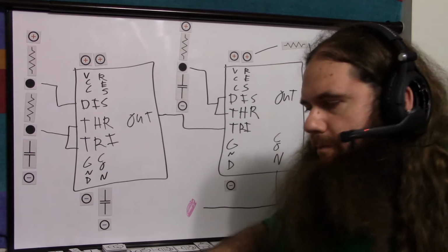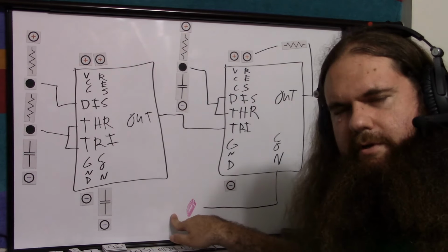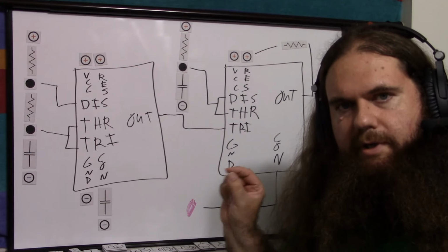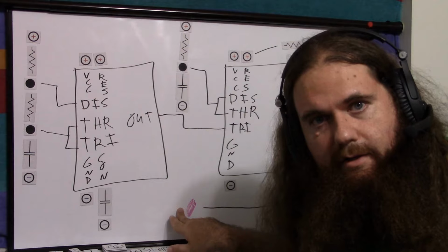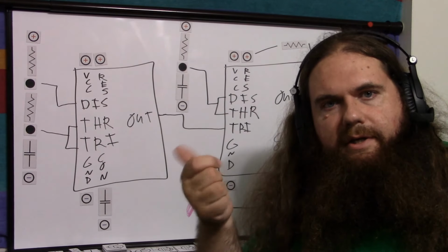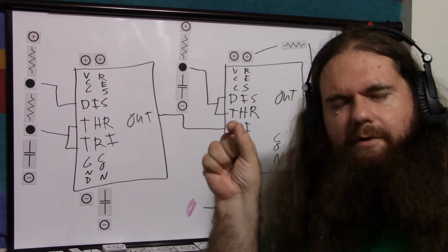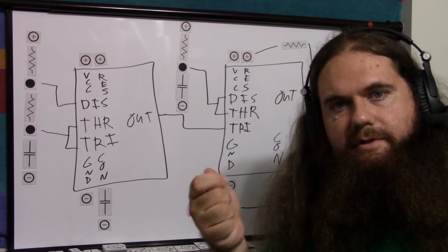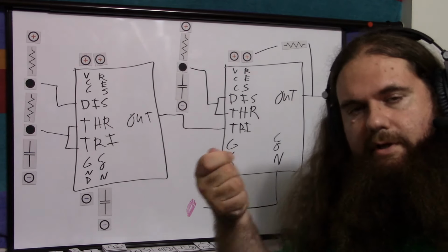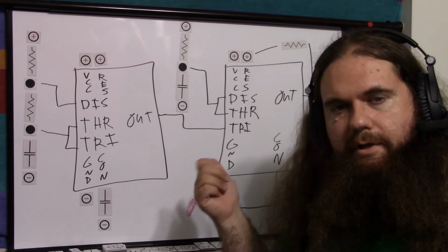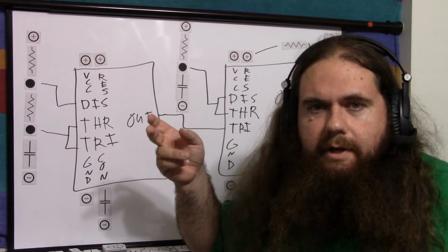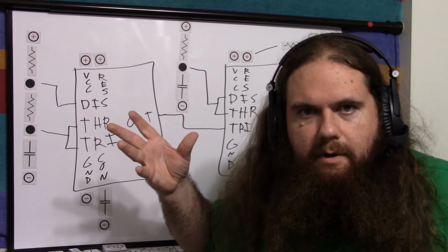And there's your PWM. And if you have some sort of microcontroller that can output an analog voltage, or you have a DAC, some sort of digital to analog converter, or even a potentiometer, you can do it with a physical knob. You have a potentiometer acting as a voltage divider and apply a voltage. And you can just have a knob turning it up and down. Any way you apply a different voltage, you can control this. Now, if you use an Arduino, it just outputs PWM automatically.